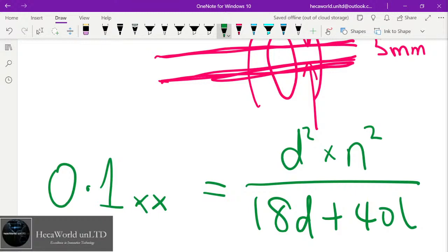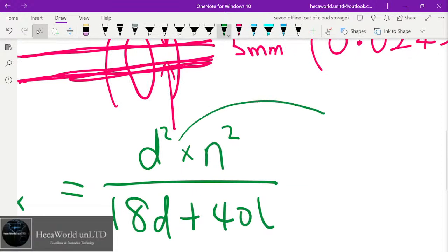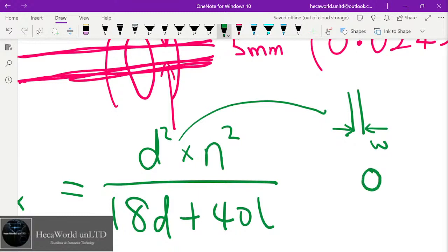So what I'm going to do is I'll take the wire because I will have the wire already in my hands. I'll take the wire and I measure the W of that wire. And then I'll determine the circumference of the object that I want to make the coil out of. So that X plus my W will give me my D. So I can plug in my D here right away.